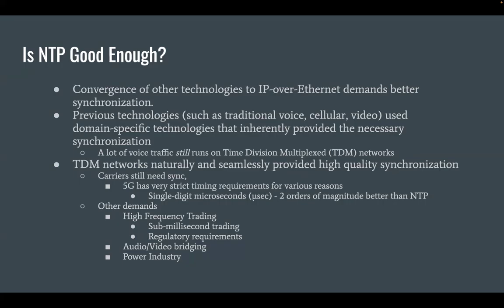But the benefit of those previous technologies was that they used domain-specific features that inherently provided synchronization. I mean, after all, T1s and SONET were time division multiplex networks, so you could easily and natively and naturally derive time and frequency, or at least frequency and phase synchronization from those underlying transport technologies.